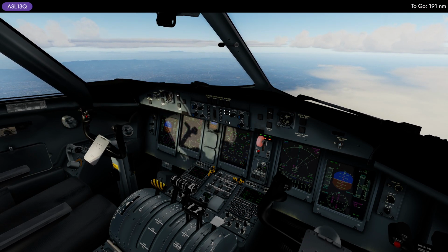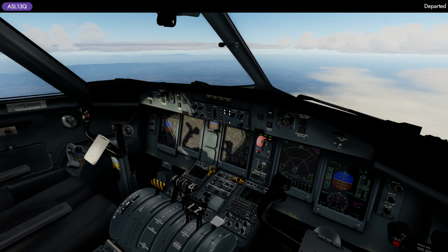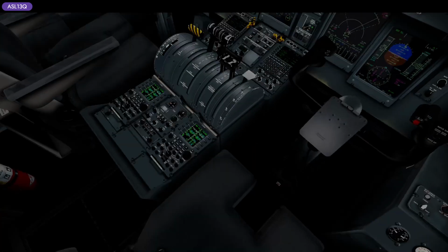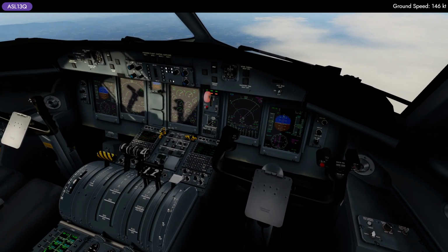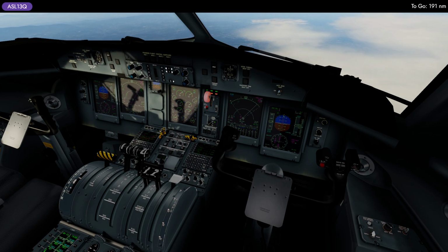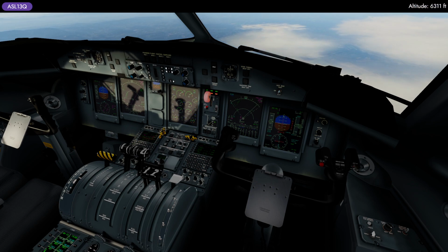I'll need the ILS frequency for Zagreb, which is 109.1. So let's go 109.1. There we go. The final course is going to be 223. So we can now switch there and give it 223. There we go.